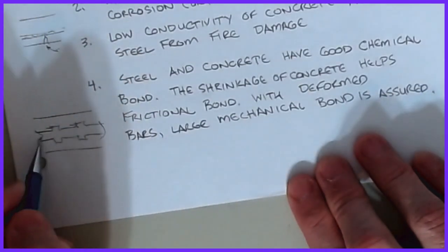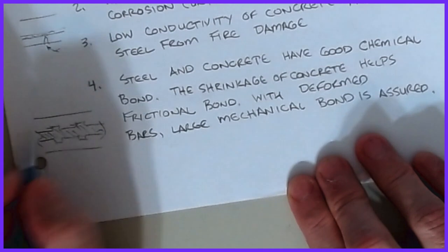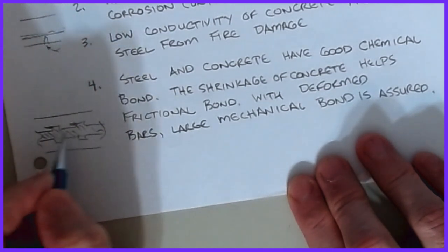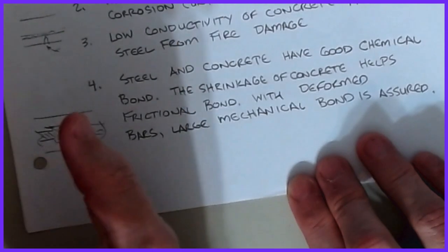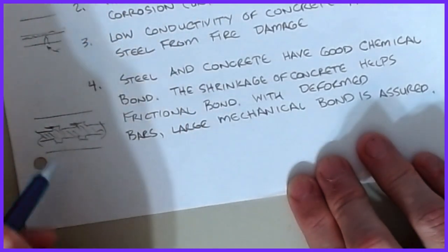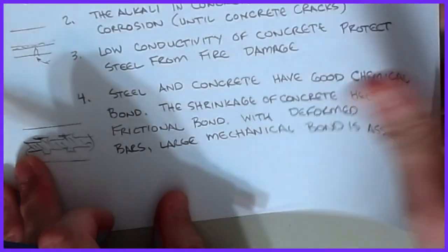I apologize for that. So here's my rebar with the ribs shown on it, and I pour the concrete around the outside of this thing, and as it starts to shrink, it starts to push on these ribs, which then helps to reduce the amount of strain that the concrete wants to undergo. The bars actually help to prevent it from shrinking too much and developing those tensile cracks. So this reinforcing steel for shrinkage is very, very important as we start to look at that.